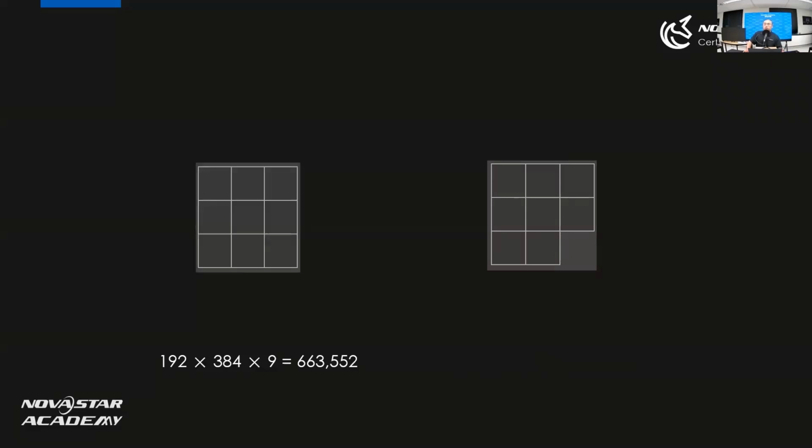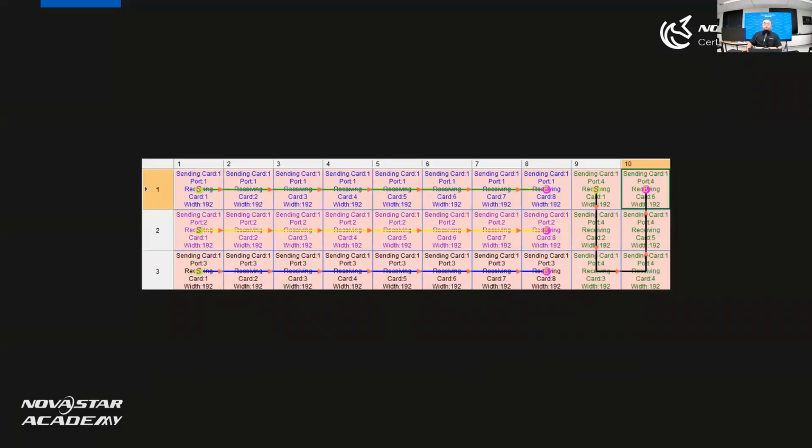Actually, not. From this new screen connection, we can see we keep one output connecting 8 cabinets, like this, like this. So we can change to another screen connection. Port 1 loads just 8 cabinets in the first line, and the last output just connects 6 cabinets.